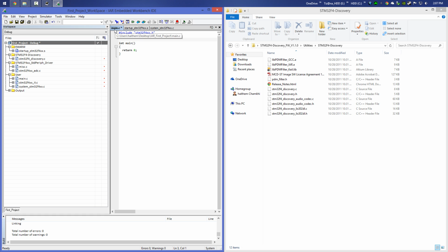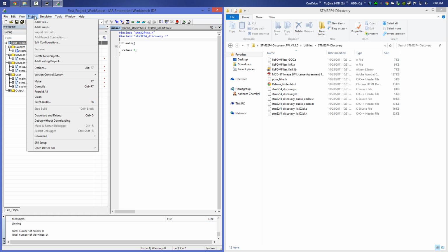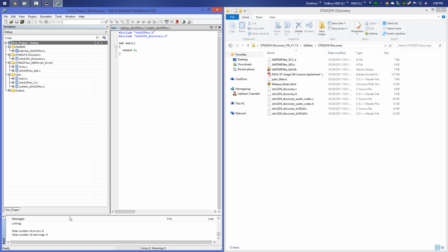You can create a main header file and put those includes inside it, but I don't want to complicate the configuration of our project too much, so we can do it like this. So we save and we're gonna try this out. We're gonna rebuild and we see if we have a problem. As you can see here, we have 0 error and 0 warning. Now we finish with our header file. Let's move on to the linker and debugger configuration.